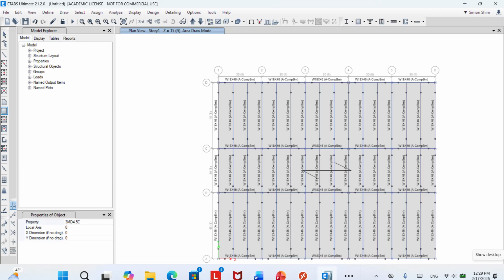So here is the thing. We talk about metal deck. It's corrugated and has a one-way direction. Metal deck is folded. It should be placed perpendicular to the beams. Otherwise, it's going to fall down. See that? It's folded. So the metal deck should be placed on a series of beams on top.